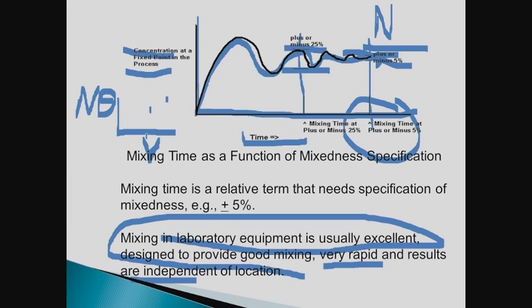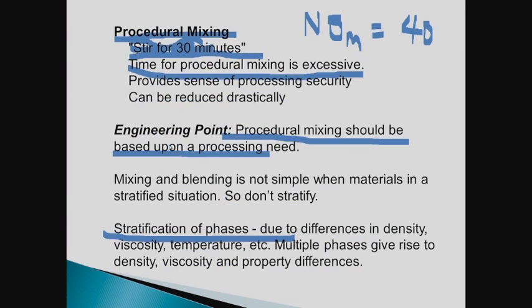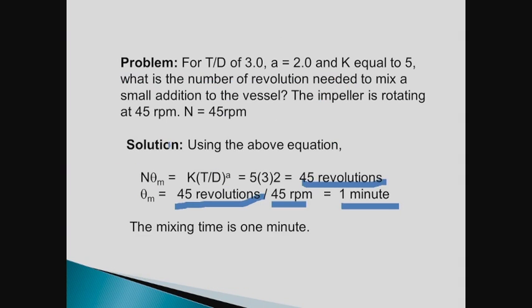Then you come along, you get another data point. Come along, you get another data point. So you then have your N theta values calibrated as a function of volume for different impellers. I mean, different tanks. You calibrate your whole plant that way. Of course, you won't. I was talking about N theta with one company, and they got very enthused. And the next day, when they came back to work, they had 1,000 tanks, and to calibrate their 1,000 tank plant, that was tough work.